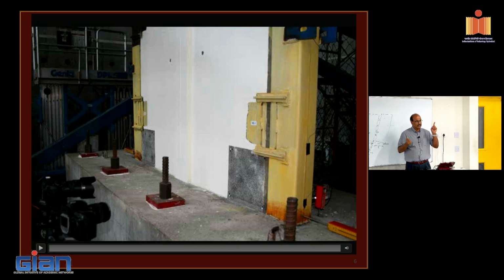This is a mild steel, that's a stainless steel, because that goes through a much larger strain, so they prefer stainless steel plate. And with stainless steel, I don't know about here, but if you're welding stainless steel to embedded regular steel, then you need a specialized welder and a specialized inspector. The cost just keeps going. This is as simple as adding plates. We add the plate on both sides, and stability-wise, it keeps things together as well.